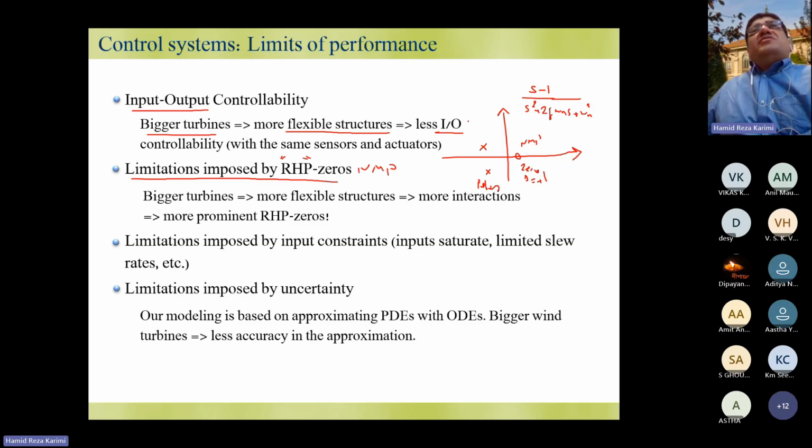The problem is that NMP gives you a 180-degree phase, so 90-degree phase. And that's it, the system has very bad performance. The system becomes very oscillatory, and therefore you cannot compensate. Compensation of these zeros is difficult, because these zeros remain on the right side and they destroy the performance.